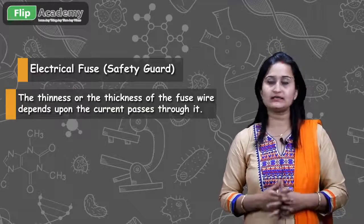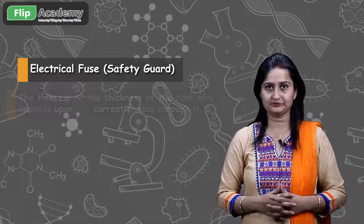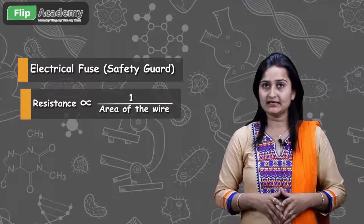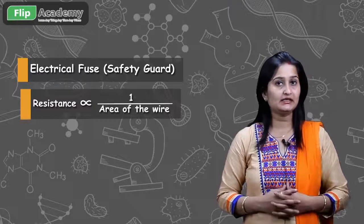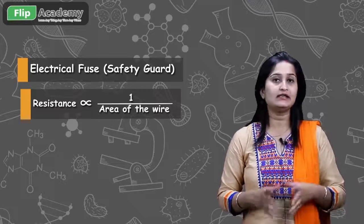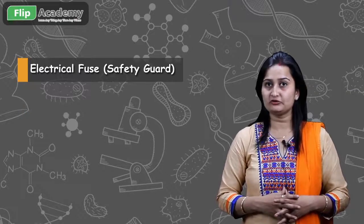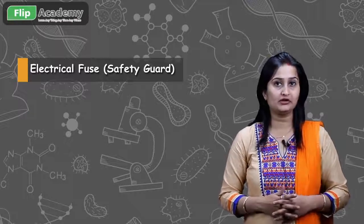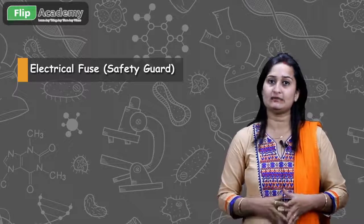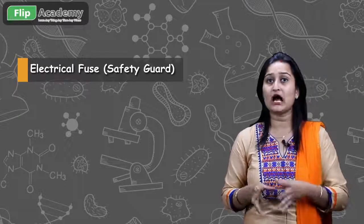The thinness or the thickness of the fuse wire depends upon the current passing through it. The resistance is inversely proportional to the area of the wire. That is, if the fuse wire is thin, then in that case the resistance is high. If the fuse wire is thick, then in that condition the resistance is low. In the market, if you go to purchase a fuse wire, it comes in proper current ratings. That is, starting from 1 ampere, 2 ampere, 3 ampere, 4 ampere till 10 ampere and so on. So, depending on these current ratings, fuse wires are available.